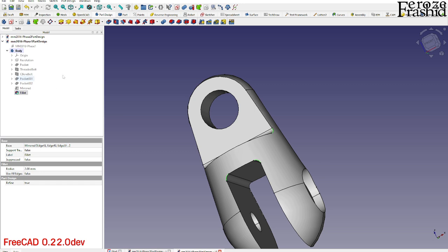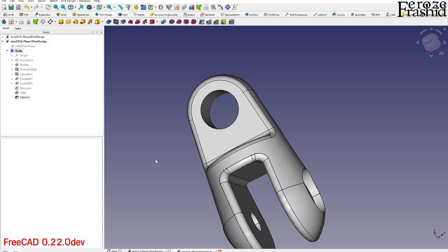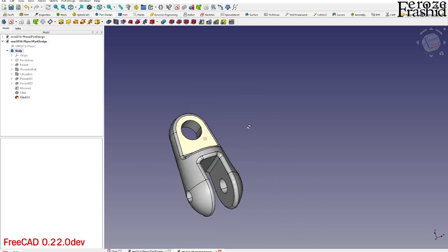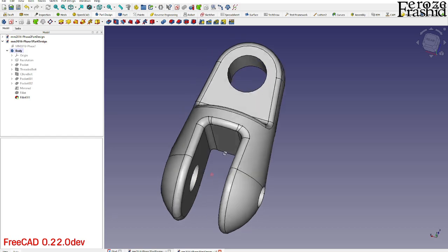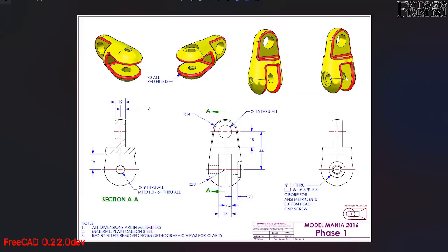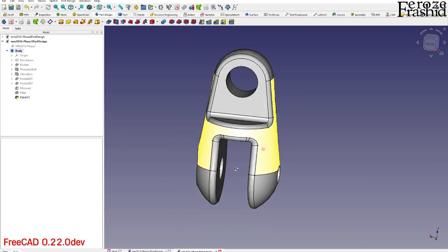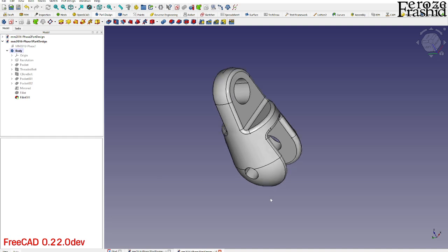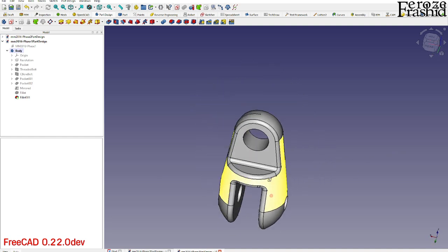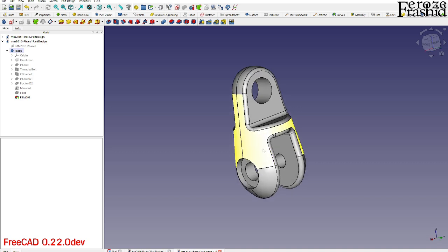Maybe taking one of them would also work, but come here and then say another 2 millimeter fillet. All right, so that's essentially our model, phase 1, built up to the spec 100% of what it asks. 2 millimeter fillet all around, and pretty cool. So this is the end of phase 1.